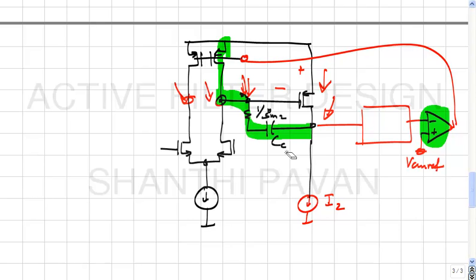Why is it not helped by a large error amp gain? Because last time we saw that even if the loop gain is high... Right. If you now end up putting a large gain here, you will find that you are introducing an extra pole, which now becomes a third order system, becomes extremely messy, and probably difficult to compensate. So, it is simply straightforward to have a low gain error amplifier. There will be a finite offset from the common mode reference.